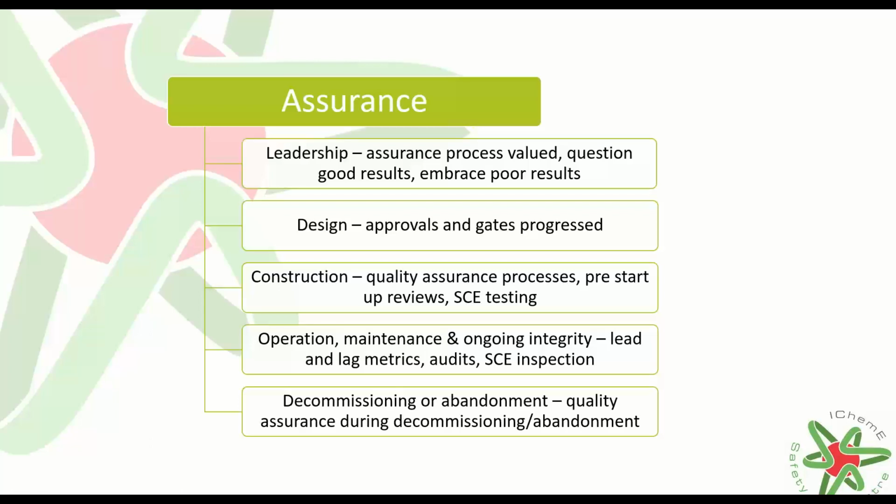From a design perspective, we need to make sure that all approvals and appropriate gates are progressed as we go through that process. In construction, we need the quality assurance processes. How do we know that every weld has been non-destructively tested to know that it is a good quality, for example? Pre-startup reviews, making sure that everything is aligned before we start the process. And safety critical element testing, making sure that we understand that the safety critical elements are functioning adequately. From operations perspective, lead and lag metrics are indicators, so understanding what's actually going on in our organisation. Having our audits in place and having our safety critical element inspection as well.